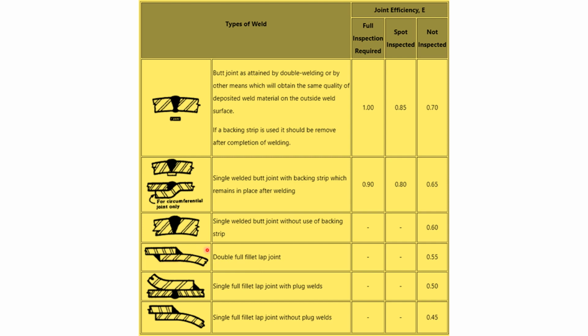You check it corresponding to the different thicknesses. It is given in the ASME Section VIII Division 1 very clearly in UW, how much lap is required here. Normally, depending upon thickness, we take 2 times the thickness, or 3 times the thickness, for the overlapping, and we do a fillet weld here and a fillet weld here. Okay. So moving on to the next.